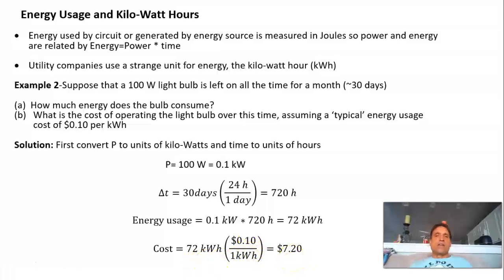So in this particular case, which is pretty close to what most, I mean, I don't know exactly what they are now, but traditionally it's been around a dime per kilowatt hour. It's about $7 a month to leave your 100-watt light bulb on all the time. So try these, for fun. Go home and check these out on different things in your house, and you can see what contributes most to your electric bill. If you own a home, it's obviously heating and cooling, as you'll see if you calculate. But in this case, $7 a month for leaving your light bulb on. Probably should turn it off.